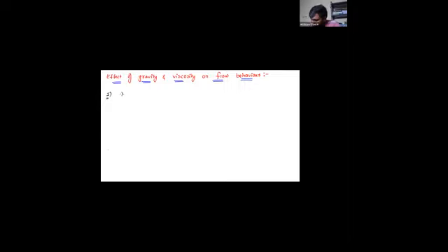So now I am going to use the classification based on Froude number. Number 1, Froude's number. And you know that Froude's number Fr is equal to V by root of gL. V by root of gL. Now, what is this L, sir? L is nothing but the characteristic dimension.